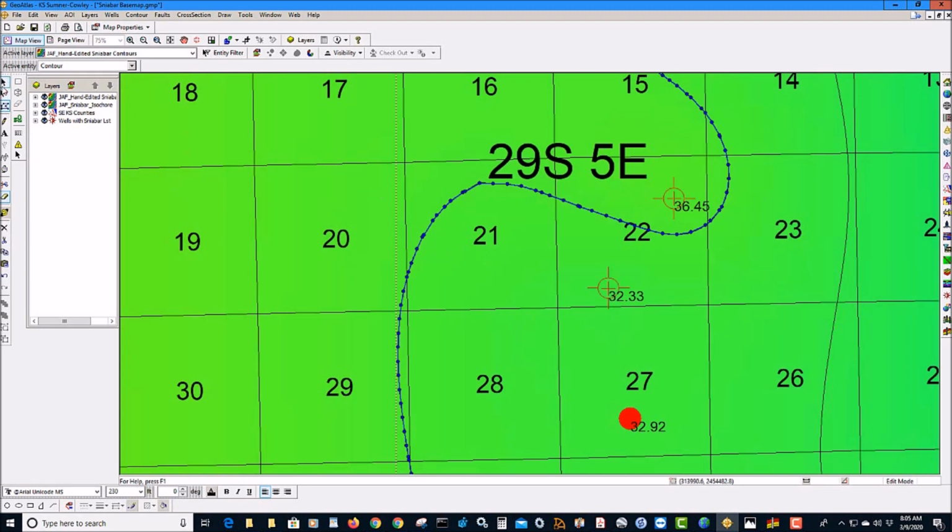And by the way, we're actually working on an enhancement where we can select a contour line and reduce the number of nodes on it so that you can hand edit it more easily. Another option to reduce the number of nodes is to increase the smallest feature radius, i.e. drop the total number of grid nodes so you get far fewer contour nodes.